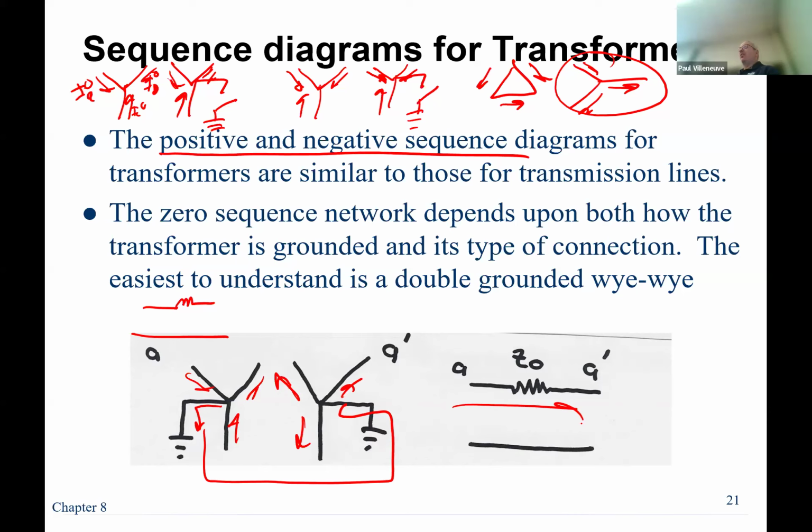So if you have a system with a grounded Y transformer, that actually doesn't help you in terms of isolating your grounds. It actually sort of connects them through the zero sequence line. So in distribution circuits, you see this all the time, but if you work at a transmission system or if you're a generating facility, you never see grounded Y transformers because it just makes things very difficult to protect and coordinate.